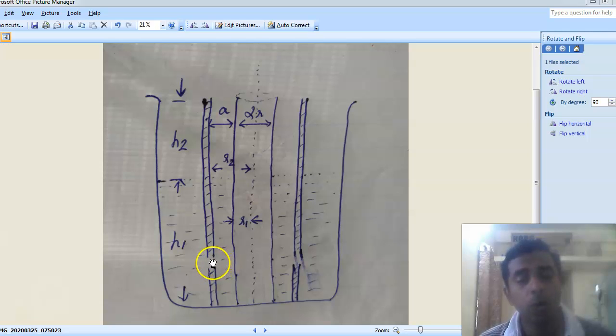Okay, so this is the figure, and there is a small hole inside the outer cylinder where the non-conducting liquid is allowed to flow. I mention it as a small hole because a small hole will not allow perturbations or disturbances in the level of the non-conducting fluid to affect the inside. That is, if the hole is small, variations in the level of the fluid will not get transmitted inside the tank. That is why we keep the hole small. But the hole is required because we need the non-conducting fluid between the two conducting concentric cylinders. I hope the figure is clear.